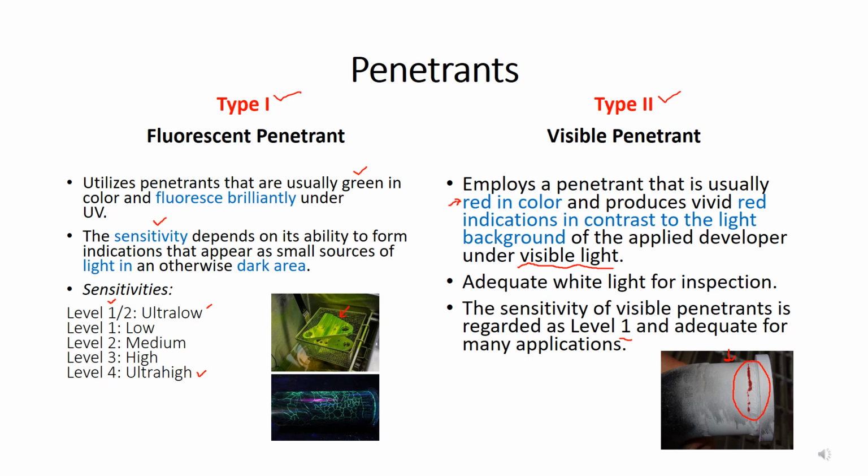If you are using ultraviolet light you can use the fluorescent penetrant, and if you are using normal white light, or the naked eye, and you are not using the ultraviolet light, just white light for the inspection, then you can choose the visible penetrant.